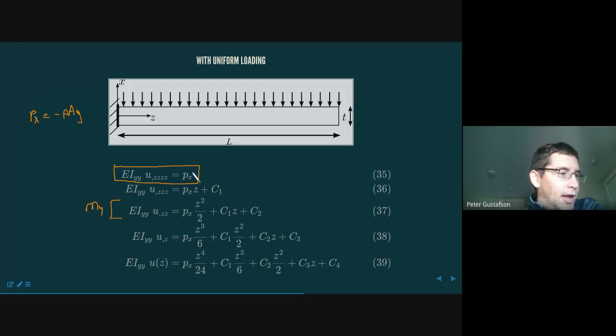So David, I think that answers your question. What I would suggest as a general rule is that the equation as written and boxed here is the definition of the equation. I would solve the equation as written, and then ultimately when you plug in the known distributed load, track your sign in the known distributed load.